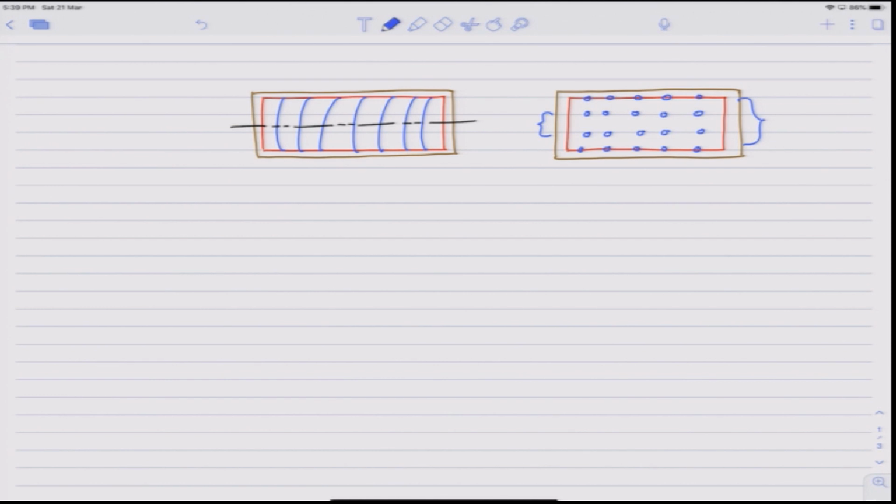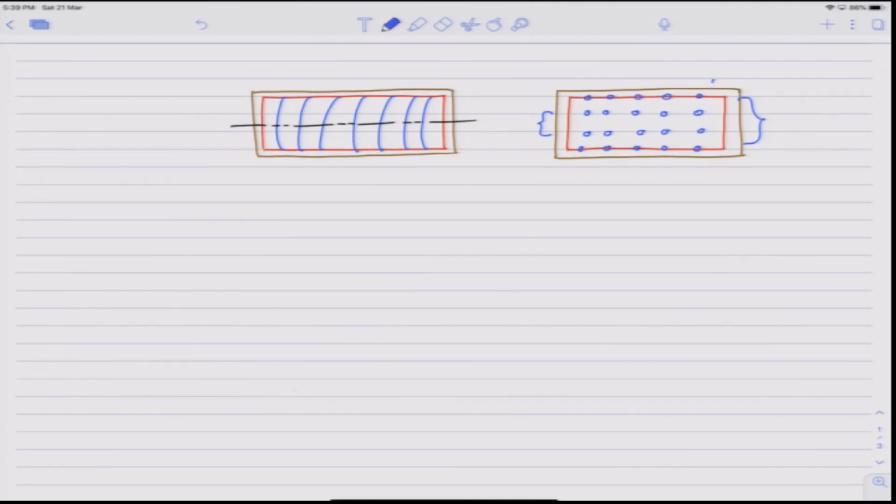Since copper was diffusing from outside into the brass and the zinc was diffusing from brass into the copper, obviously this would have occurred because of the faster diffusion of zinc from inside out compared to the diffusion of copper from outside in.